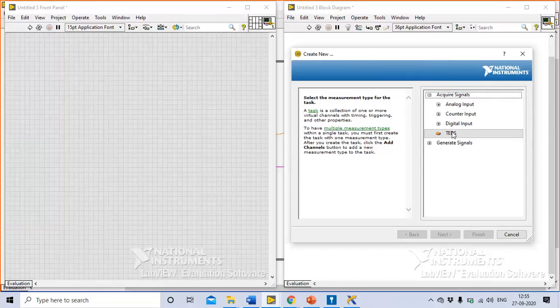There are a lot of sensors which have an onboard EEPROM. On that EEPROM, they basically put a small file, which is the electronic data sheet of that sensor. So in various mission critical applications, let's say we are validating a satellite which needs to be launched into space. For that satellite, they are using a sensor to characterize, let's say, the vibrations of the satellite, whether it can bear vibrations of 2G, 3G, 5G, 50G, which it will go through during the launch stage.